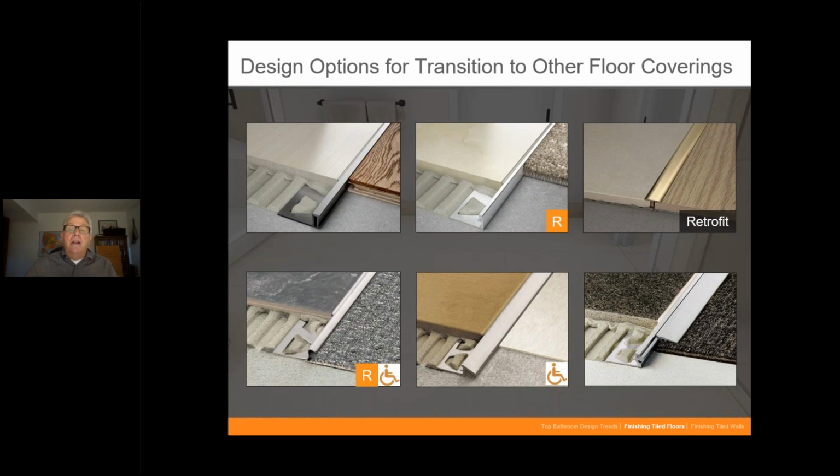on the market. That R designation also means that that profile can be snipped up and turned into a radius. If you don't have a straight edge, you have some sort of arc or radius that you built into your design, those products can actually be snipped either by the manufacturer or it can be done on the job site, and you can actually put a curve into there.